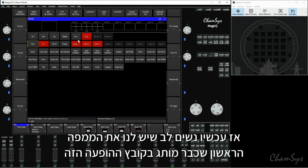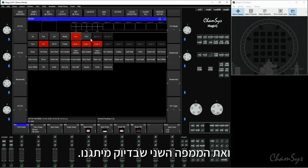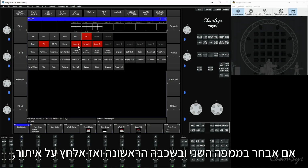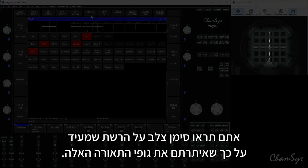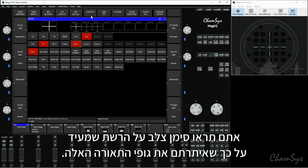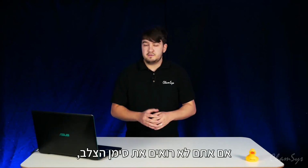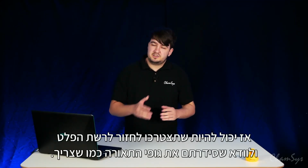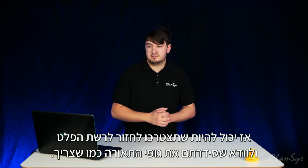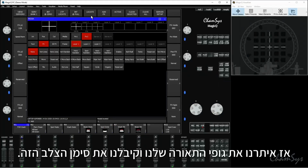So now we'll notice again we've got Pix1, which was already patched in this show file, and then Pix2, which we've just patched here. If I select Pix2 and select the first layer and press locate, you should see you get a nice cross over your grid to show that you've located those fixtures. If you don't have a nice cross, then you might need to go back to your output grid and look how you've arranged those fixtures in there. Maybe they've been arranged incorrectly. So we've located our fixtures and got this cross.